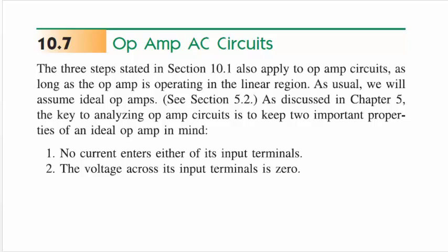Op-amp circuits also are still operated, well, at least when they're operated in the linear regime. We can do the same type of analysis as we did before for op-amp circuits, and we make the same assumptions: that no current enters either one of its terminals, and the voltage across the input terminals is 0. So, no voltage difference between the 2 terminals. Those are the 2 most important things to keep in mind, and then analyzing an op-amp circuit is just like analyzing any other circuit,